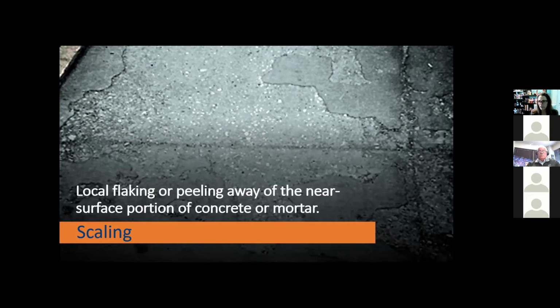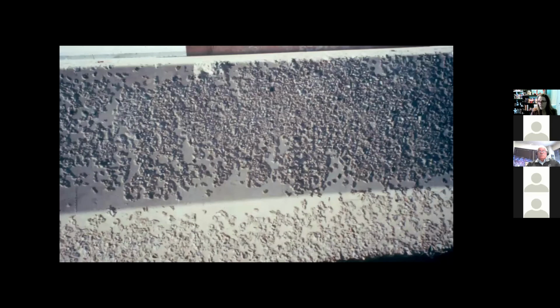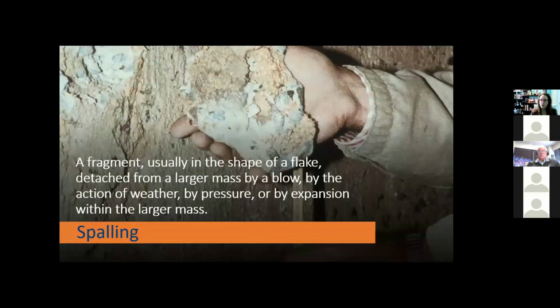So I care way more about your water cement ratio, and anytime you're designing in a de-icer climate, your water cement ratio should be less than 0.45, and if there's reinforcing steel, then it really needs to be less than 0.4 for corrosion resistance. Scale is very common in our industry, and it's something that we can design our concrete to a higher bar. And again, I did mention that we get scale in marine environments. We also get scale on vertical concrete due to snow plows and cars driving past a bridge abutment, where you can get the salt spray in that manner as well. What you do to prevent scale is sealing the surface and designing your concrete to a higher bar. If you already have scaling, it's just a choice if you want that overlay.